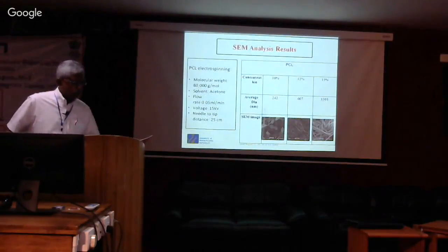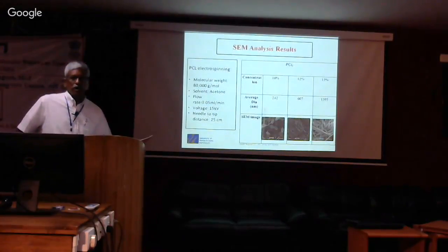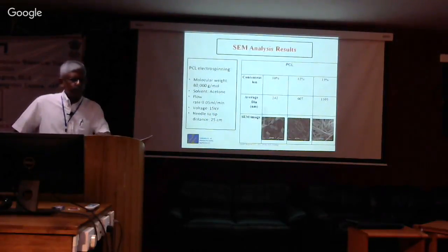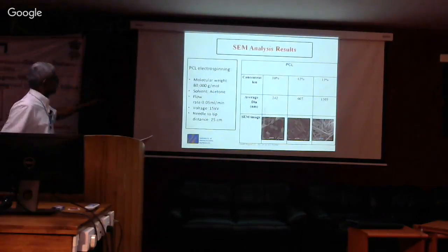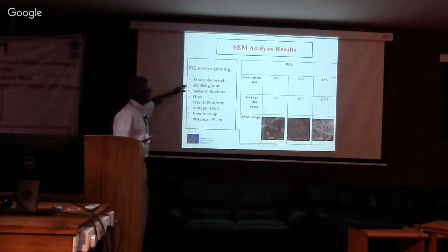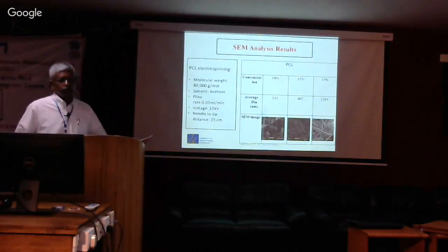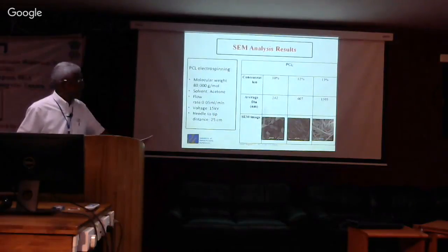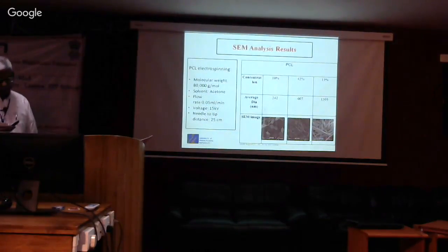Apparently, when you supply polycaprolactone, based on how the chemical supplier makes it, the molecular weight would vary anywhere from 60,000 to 120,000. And so you have to know that. In our case, 80,000 was fine, 100,000 was not. So these are some of the things which one has to keep in mind.